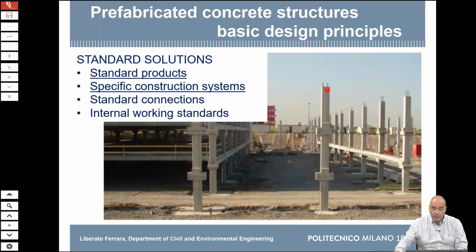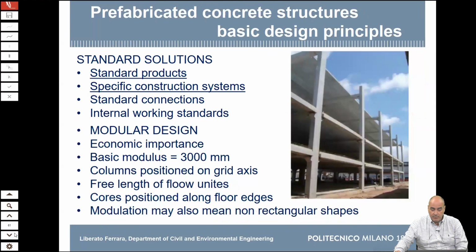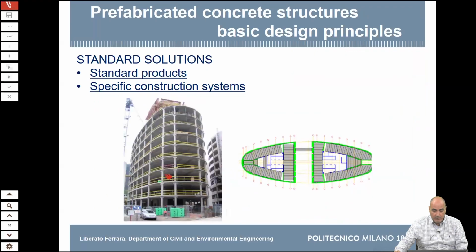You see, if you have to go higher, here is where you are going to connect the column of the top floor to the existing columns. You can see here some other things. Nowadays we use 3 meters as a basic module, so we have elements in multiples of 3 meters. And this is the module that we have used in our system.